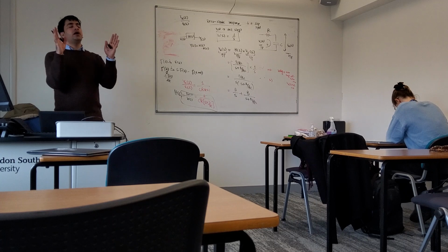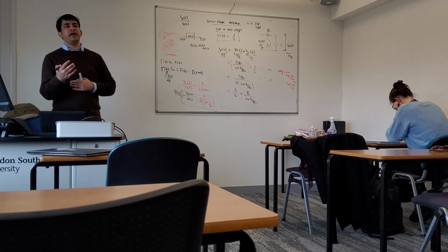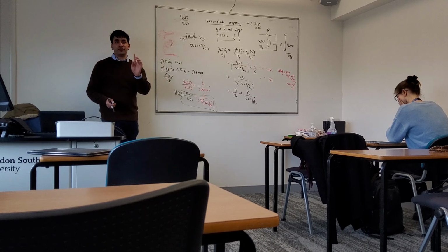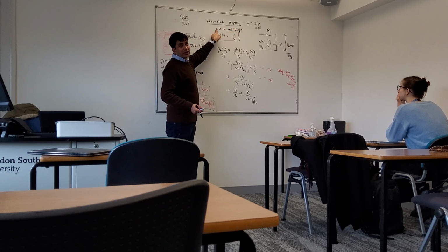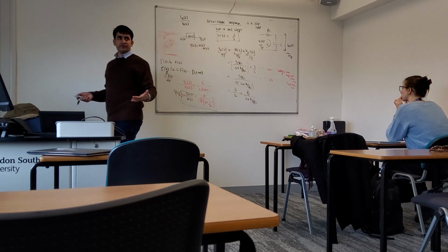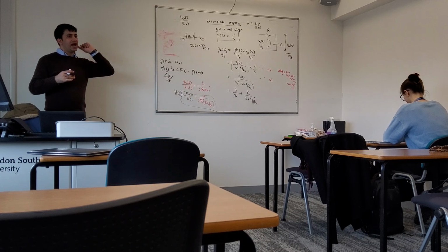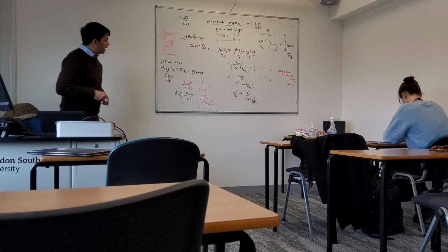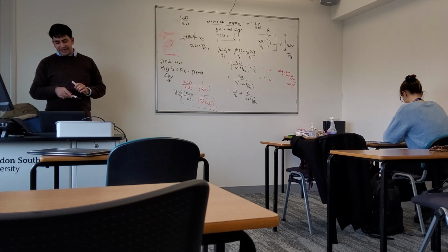If, for example, you are given a differential equation and you are being asked to find zero state response to maybe something else, you are able to find it. And how are you going to do that? The very first step would be to write the transfer function. The next step would be, whatever you are asked, take that corresponding input, find its Laplace transform, put it in this equation, then finally take inverse Laplace transform, right? Whenever you are asked to find zero state response to certain thing, you have to take that input, and that would be a very known input. You would easily know what its Laplace transform is. So for this, I can easily solve partial fraction. I can find A, and I can also find B.